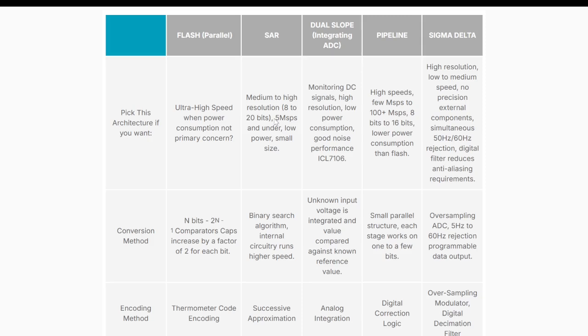But I recall this, I used a sigma delta, not SAR. And I think the conversion rate was less than 5 mega samples per second. I think it was 1.5 when I used a 24-bit sigma delta, between 1 and 2 mega samples per second. So yeah, just read through it.